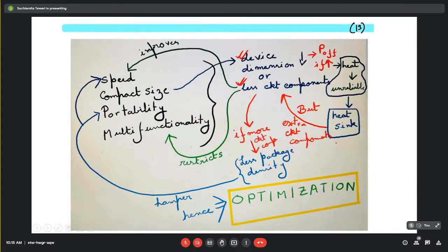We know the basic element for a gate is always a CMOS, and CMOS consists of an NMOS transistor and a PMOS transistor. Scaling down of the device means we have to scale down the individual NMOS and PMOS. You have already studied, I guess, in your class of MOSFETs or semiconductor devices, that when we scale down the device dimension, mainly the channel length, beyond a certain value, certain adverse effects come into play that we call short channel effects.